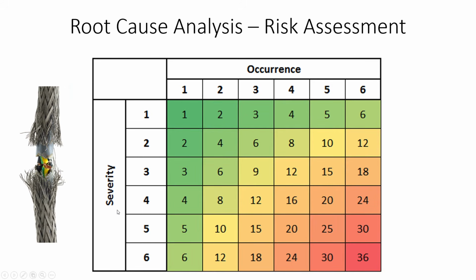So if you're measuring parts or if you're quantifying defects, all of that information should get put back into a risk assessment, because ultimately at the end of the day, remember, all of your corrective actions should be risk-based, and risk should be one of the major driving factors in the depth of your analysis and all sorts of different factors in this particular process. So don't forget about risk.